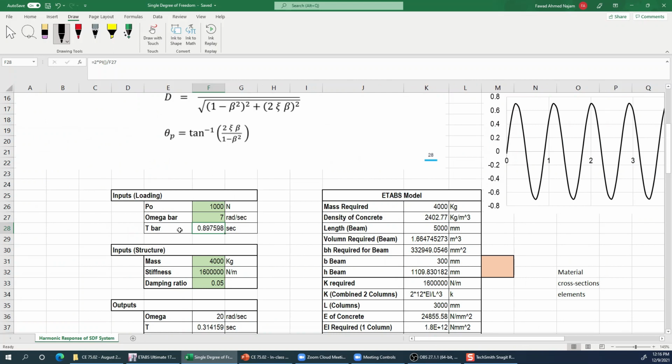But actually, it should depend on the actual loading scenario, right? For example, in case of harmonic loading, even if you know that the loading may remain for many minutes, at least you should run the analysis for that much time, in which the structure, if it wants to resonate, can have that phenomenon, and the model can capture that resonant phenomenon.